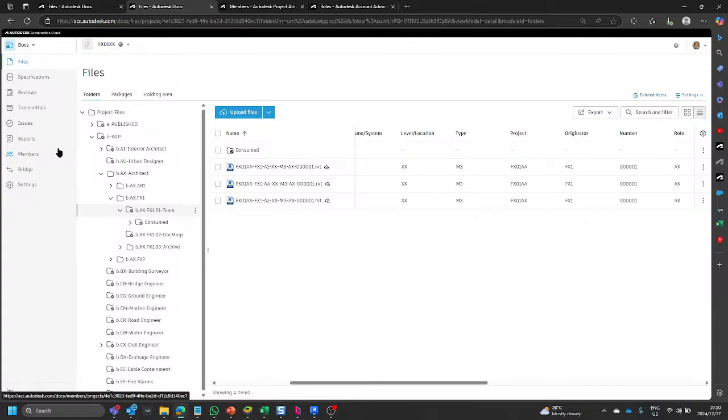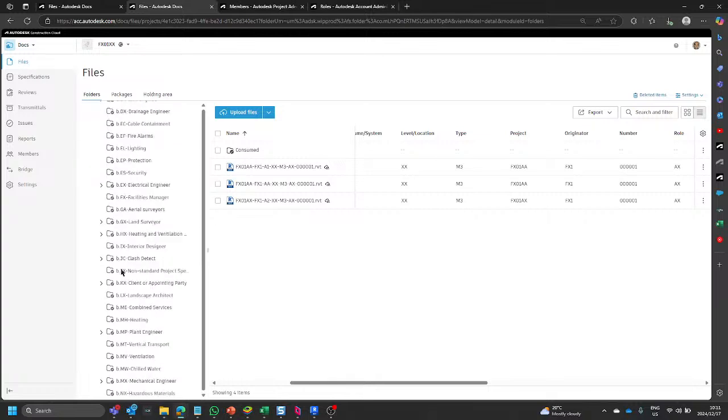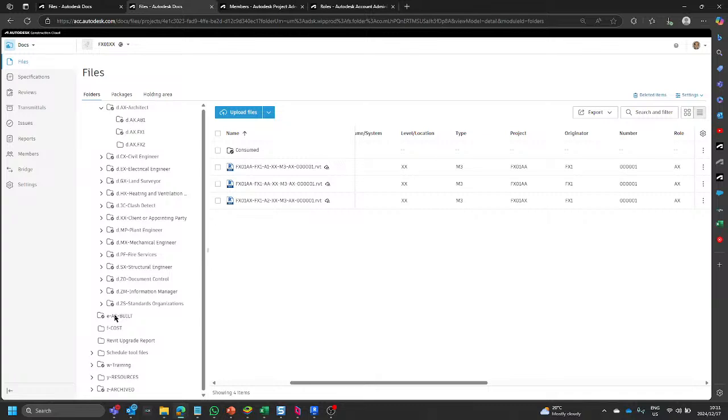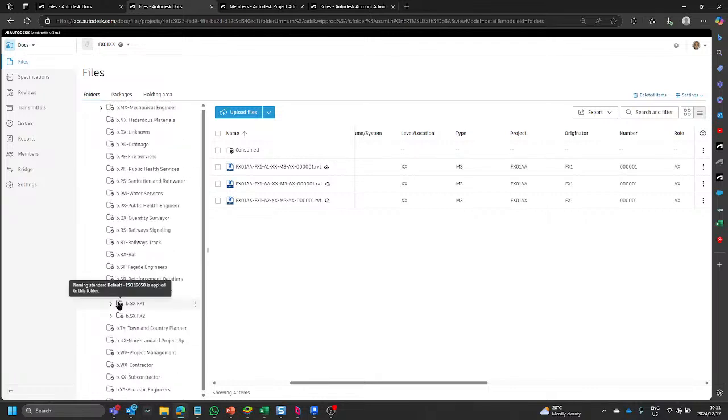Now, this process that we've just discussed is seamlessly managed by Autodesk Collaborate Pro and Autodesk Collaborate, because they've got that collaborate ability within the teams and within the swim lanes and within the timeline. So what happens when we don't have access to that? Well, I maintain that it is a good practice to preserve the folder structure, so that the same process can be followed. So we will still work under the assumption that our team folder is our silo, that the information that we share should be within the shared folder, and that the information that we consume should be a copy of the shared folder.